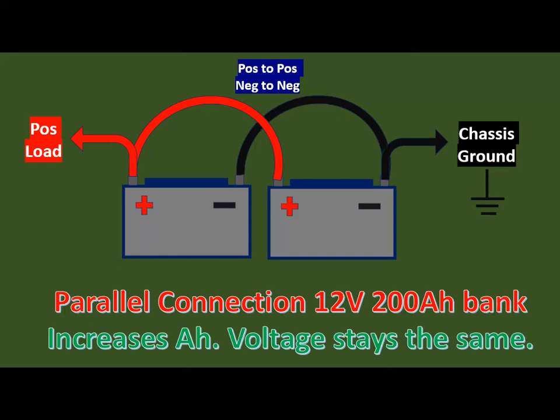It is always the best practice to use a red cable to connect the positive posts, and a black cable to connect the two negative posts. The inmost negative post of the battery will be used as a chassis ground. So the cable will be connected to the chassis in order for the vehicle to have a chassis ground.